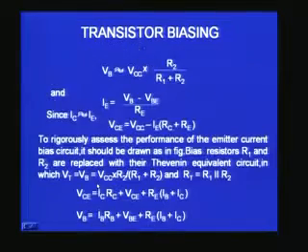If you know IE, it becomes very easy for you to know IC, because IE is almost equal to IC. The base current in a common emitter configuration is a very small component, therefore IE will almost be equal to IC. It is true for all transistors.